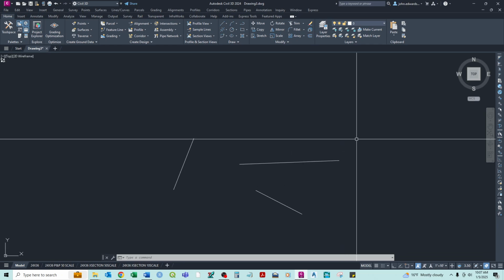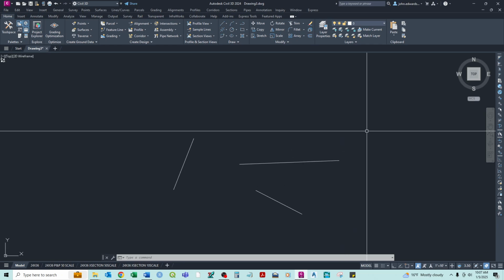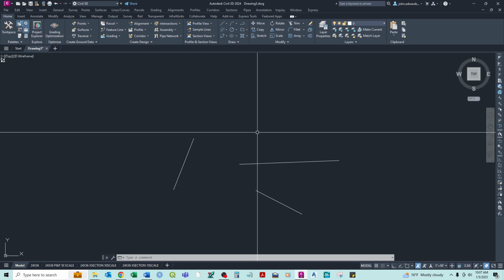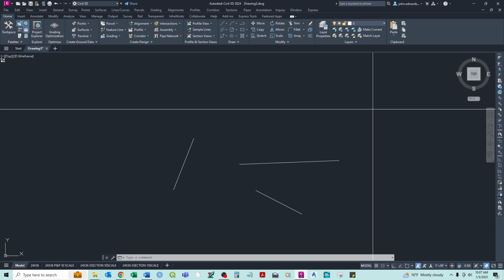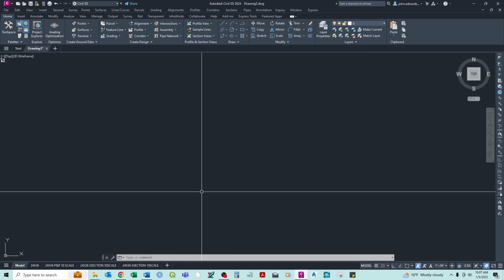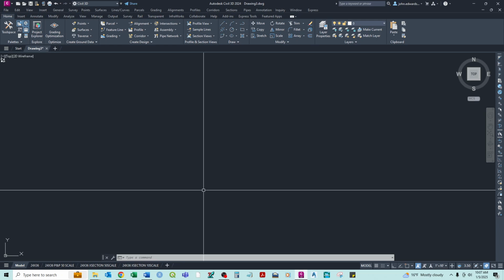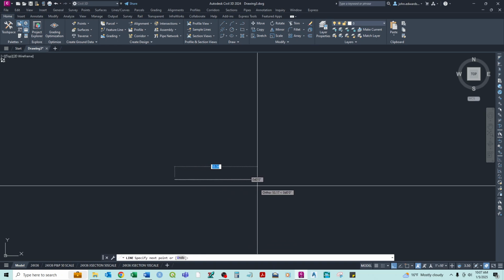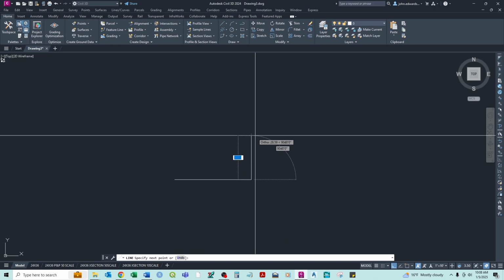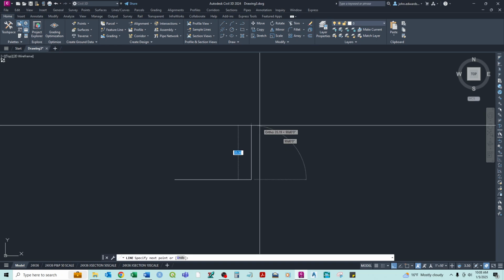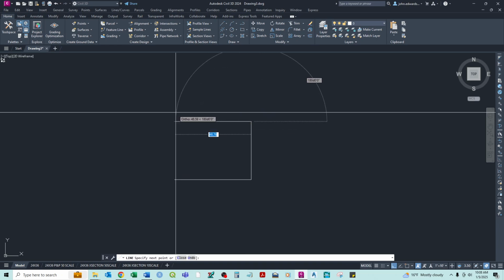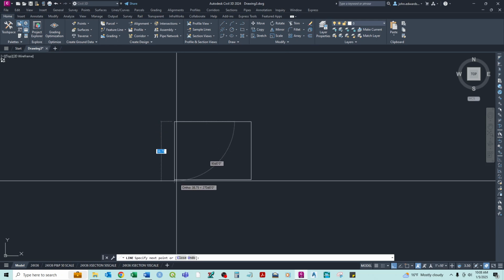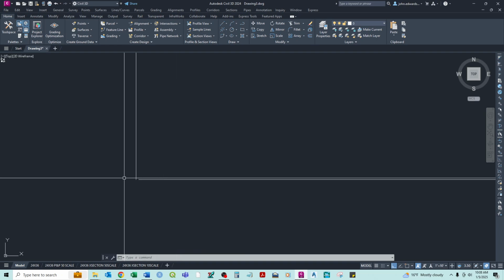And that can become very important, especially for things that need to be exact corners, exact, think about being able to hold a fluid or things like that. So there are a couple of different ways to do that. One way, obviously, if we're drawing lines, is to turn on ortho mode, so we could draw and then continue drawing, and we know that it is emanating from the previous point. But again, say I want to draw a square, it's hard to know exactly where that point is to come down and match it.